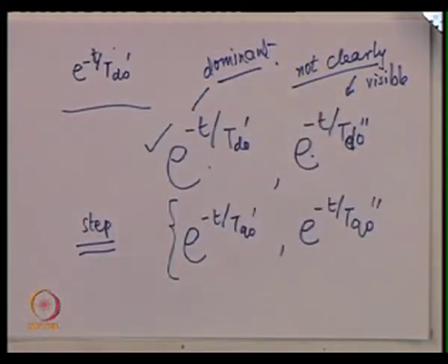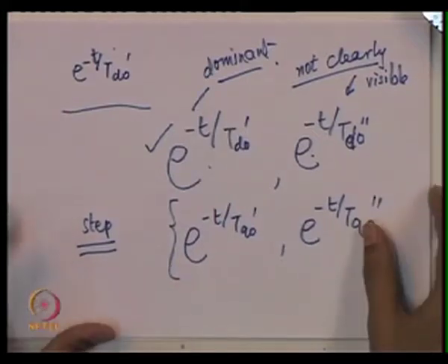So we move on now from this point to the short circuit analysis of a machine. What we need to do here is consider that the machine is rotating at a constant speed, as we have been doing so far. Then we give a step change in Vf so that you build up voltage. Once you build up the voltage and it reaches steady state, give a short circuit to the generator. So we will set RL equal to 0. Once the machine reaches its steady state, we will assume that we take RL equal to 0 suddenly.